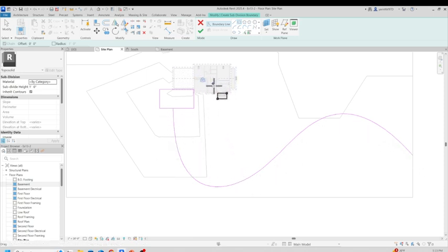So now, when we do this, let's come back, we want to make sure our driveway is about 20 feet wide, because we got a 2-car garage, 2 vehicles. You need to be able to comfortably pass each other when they're coming out. And 24 is good, but 20 is good. 20 will still do. So I'm going to come in, click the pick line right there. Offset line, and then come up here, make the offset 20 feet 0 inches, 20, enter.